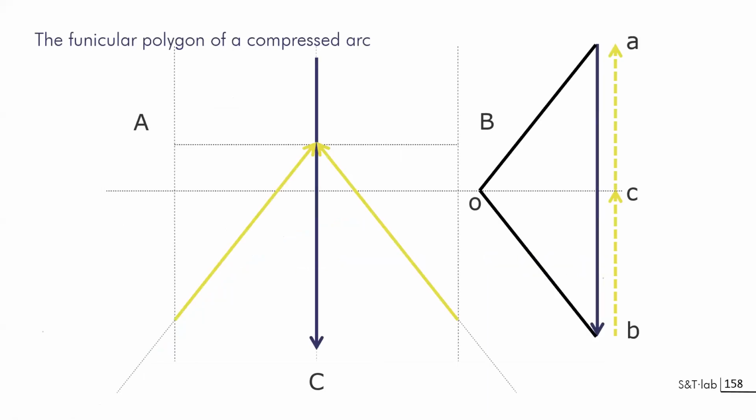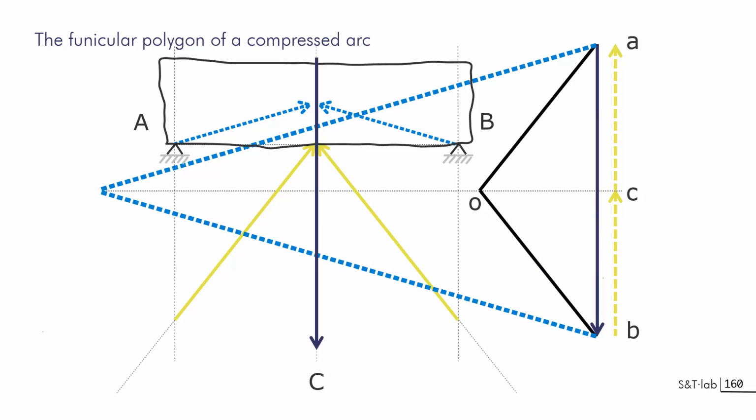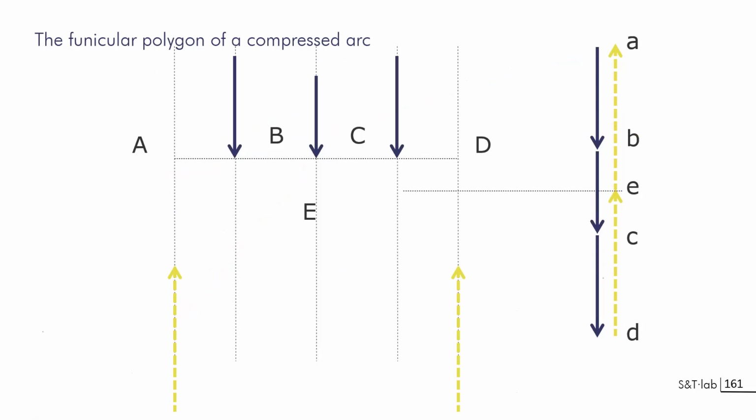Even for a system of three forces, you can build the corresponding polygon of force on the right. And you see that as soon as you move the pole of the system far away from the line of loads, the load line, the force will increase a lot. But this is the way you can represent the equilibrium of the forces in a system, in which we have the applied force replaced by the resultant at the center of gravity, and you see appearing the magnitude of forces. Of course, if you want to have smaller force, we will change stuff, as we will see later on.